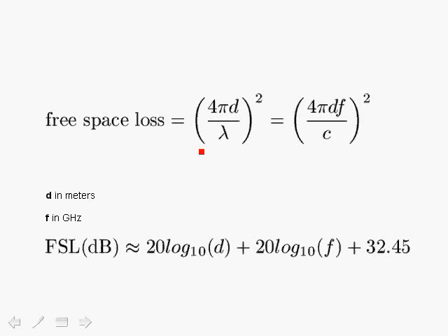As an example, in a microwave link, even though the frequency is very high, because you can use smaller dishes at higher frequencies, the antenna gain could be quite high, and you can actually achieve quite a high signal-to-noise ratio compared to cases where the frequency is lower and you don't have high gains in the antenna because the antennas have to be extremely large. So you really have to take a number of factors into consideration and do an actual link budget with antenna gains taken into consideration and the environment and of course the frequency and distance.